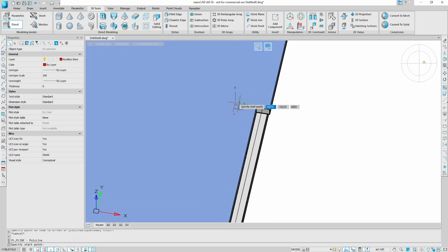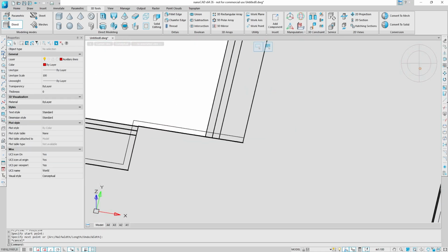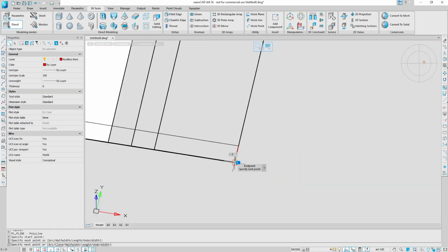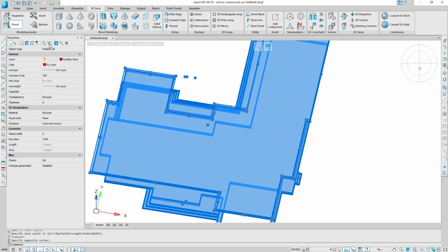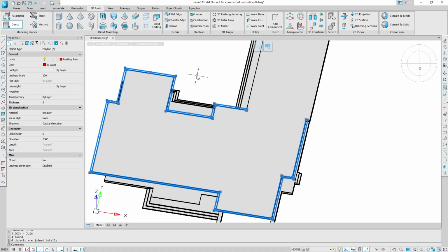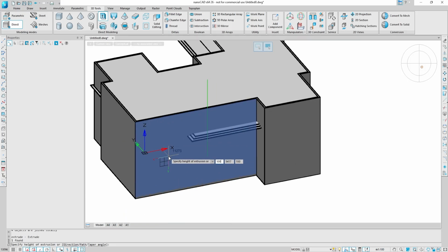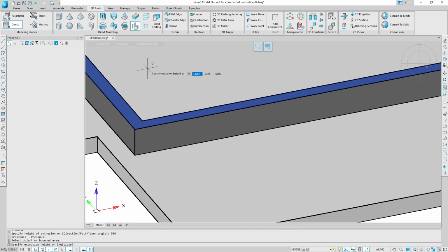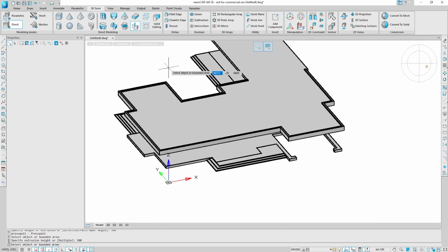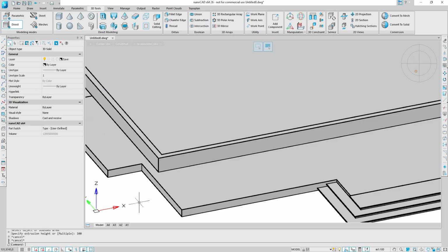Before connecting the contours, draw two additional segments using the line tool. Next, select the four parts of the contour and activate the Join command. Select a closed contour and press-pull it down by 500 mm, and then raise the upper edge by 100 mm. Transfer the resulting solid object to the eave layer.